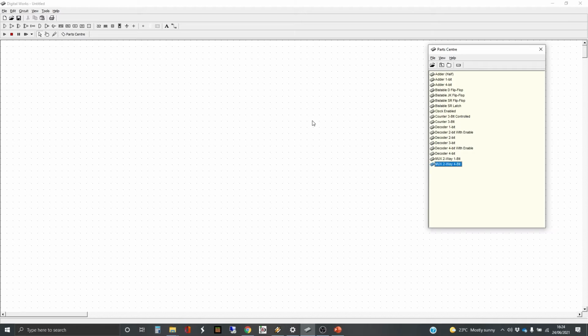So that means we've got our control signal, which is a binary input number, needs to be 2-bit. And there are 4 possible inputs. The control signal will choose which one of the 4 inputs is routed to the output, and there'll be the one output. So we're going to use the 2-bit decoder that we had previously, which is going to help us do the choosing.